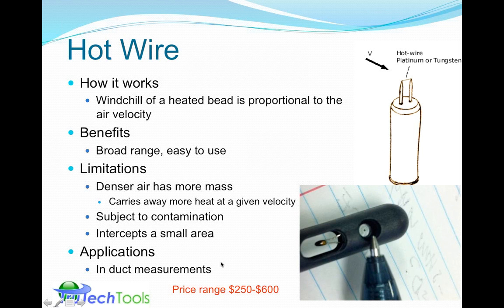And it's best used in duct measurements, where airflow is stable, laminar, with developed flow fields, versus at supplies and returns, where there tends to be a lot of turbulence. The purpose of a supply grill especially is to throw air into the room to cause mixing to do the conditioning. As it's throwing the air, it's redirecting, diverting, and deflecting it, causing a variation in its velocity profile, which makes it harder to measure at a supply.